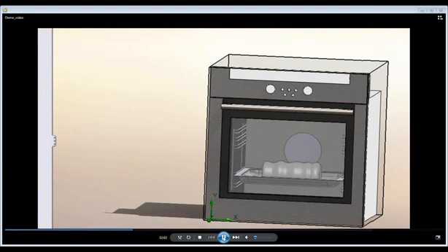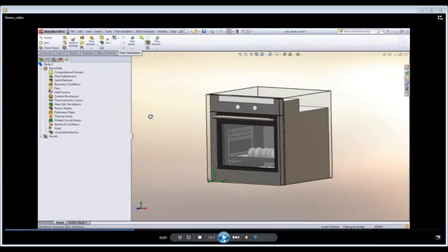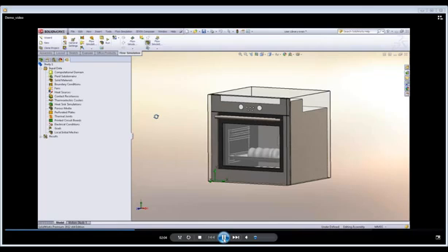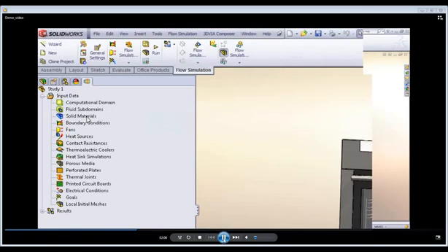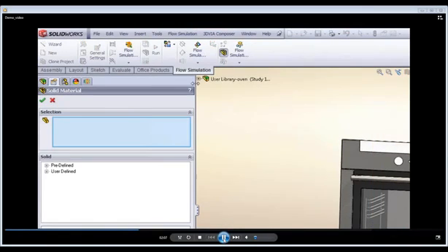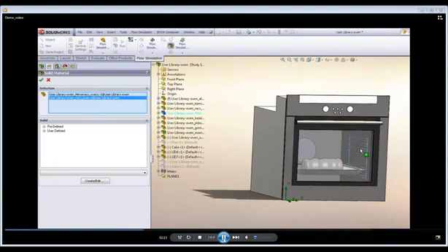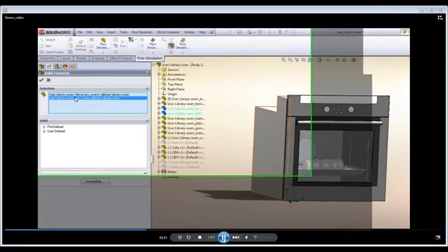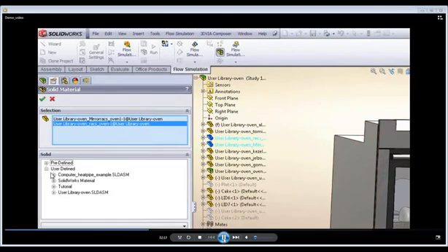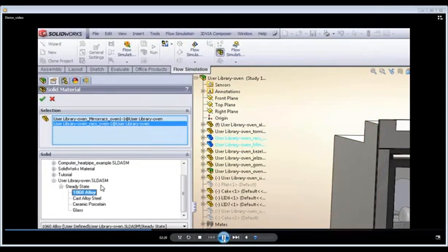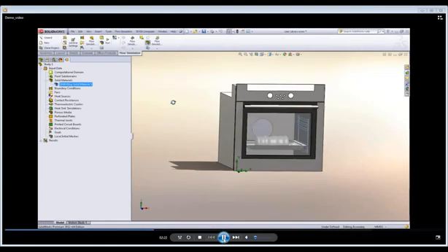Now SolidWorks Flow Simulation appears in the analysis tree, and we can see that we will define the different assumptions such as the boundary condition, the solid material, the heat sources. So we'll do that together. So next, the various material properties are defined. We already defined the default material as cast alloy steel. So a 1060 steel alloy is applied to the internal wire type support frame. So very simply, we just need to select those two parts and define the material for these two parts.